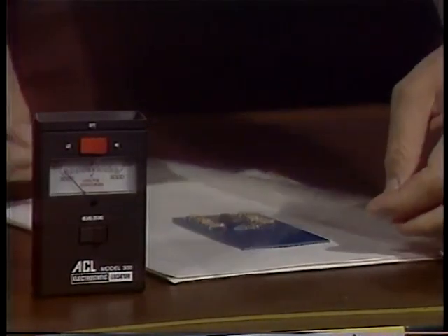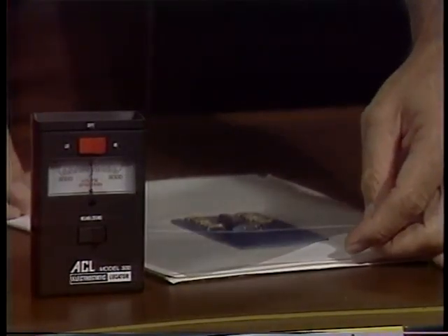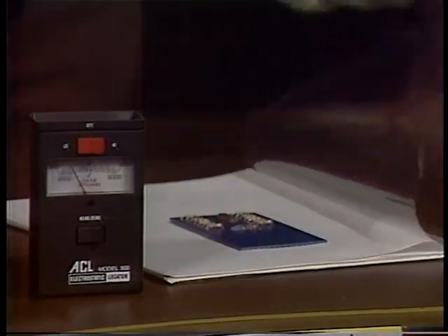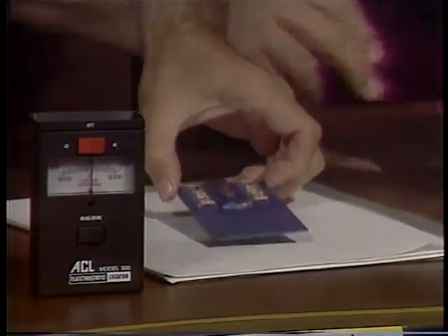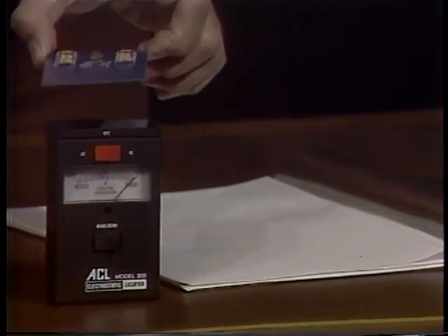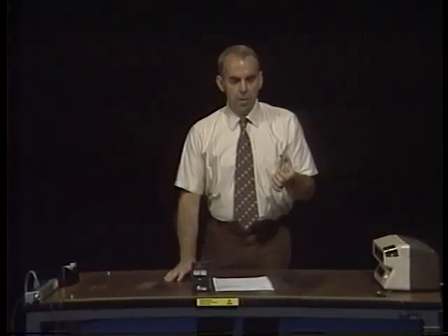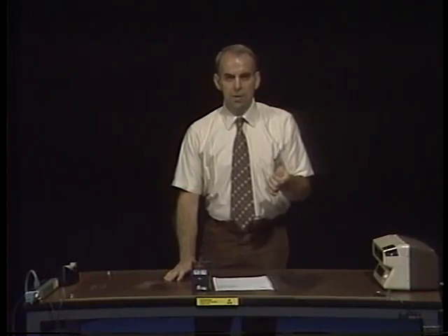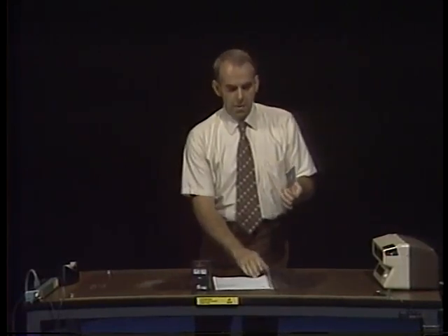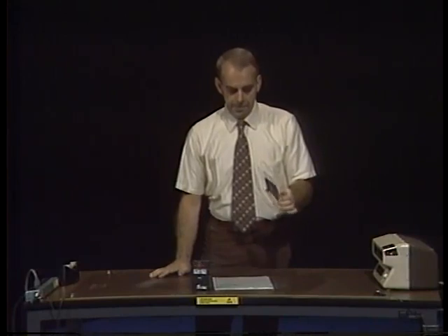even though the vinyl cover doesn't make contact with the board, when we remove the board and check it with the meter, we will find that it has become highly charged. The next time this board is grounded, that sudden discharge can result in a static zap.